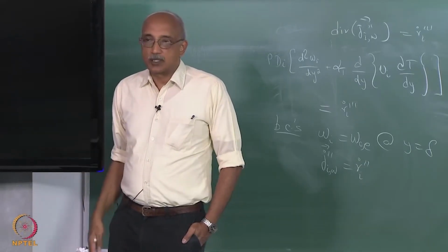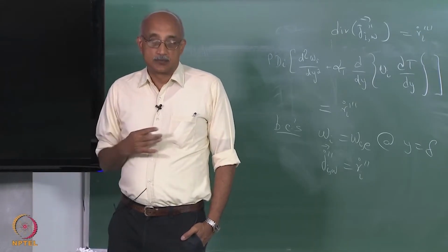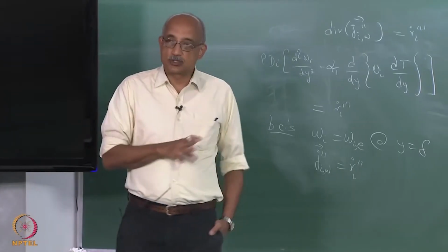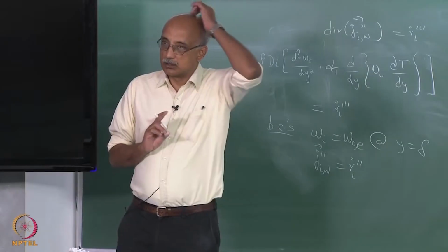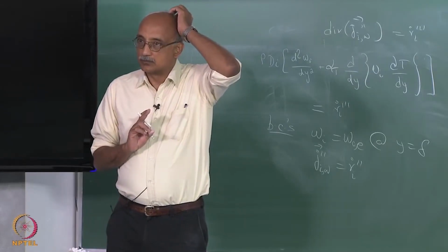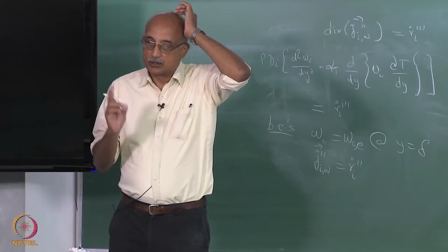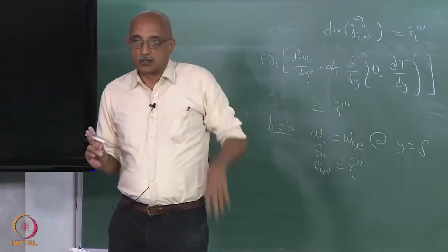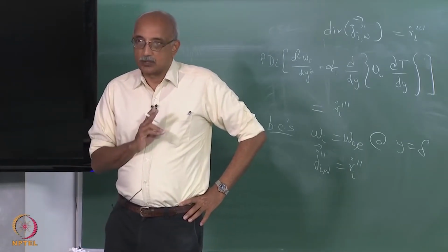If the Damköhler number exceeds or falls below a certain value, but which Damköhler number? When you look at the transition from 1 to 2, which one do you think is the crucial Damköhler number? Heterogeneous, right? And similarly, the transition from 2 to 3 will not be influenced by your heterogeneous Damköhler number, but by your homogeneous Damköhler number.